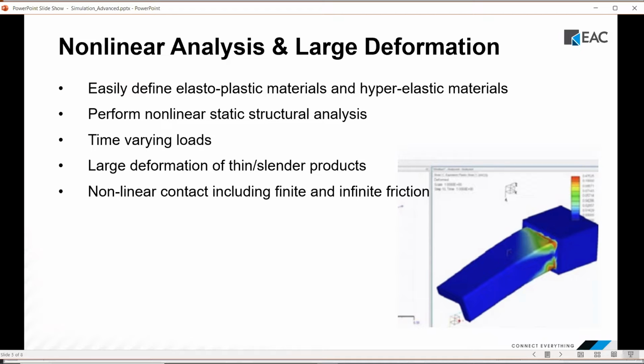That's how we do large deformations, and also deal with elastoplastic materials and hyperelastic materials. We can also do varying loads over time, and large deformations over a variety of different types of products, whether they be thin or regular type products. And then nonlinear contact with infinite and finite frictions.